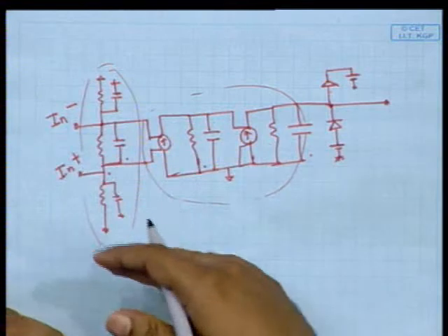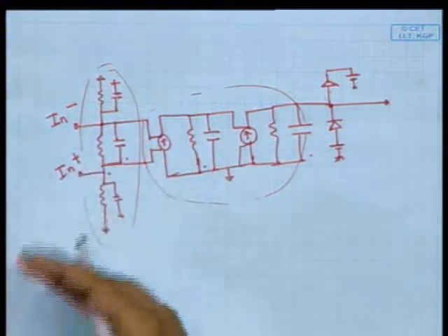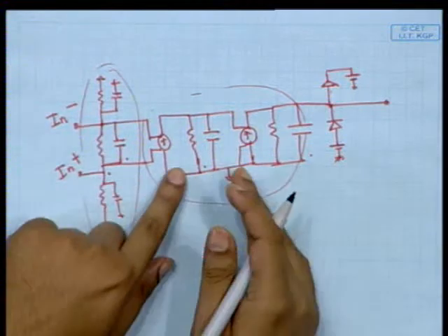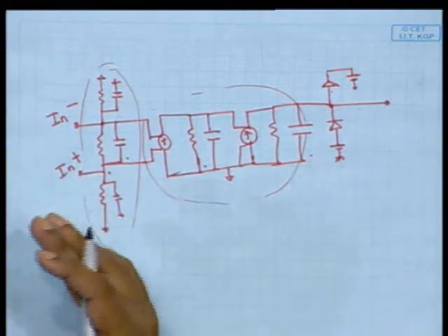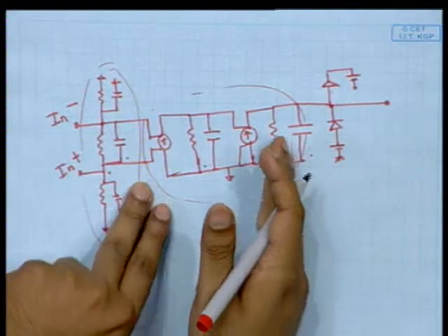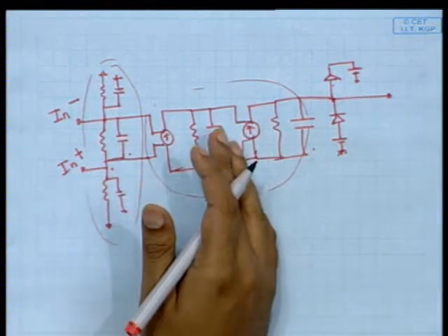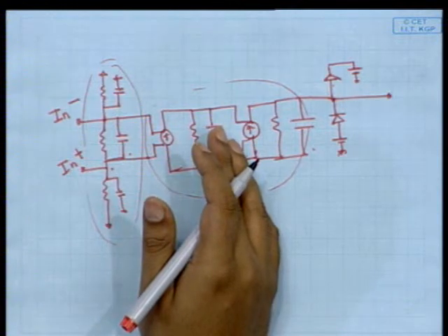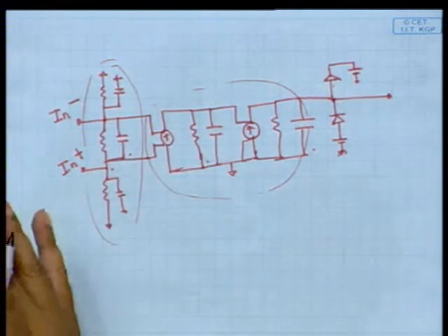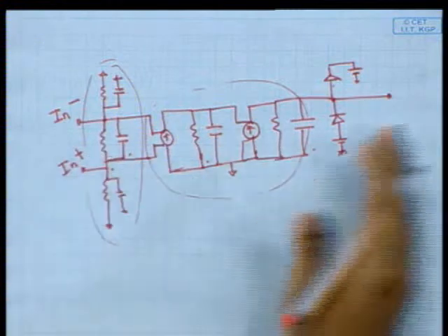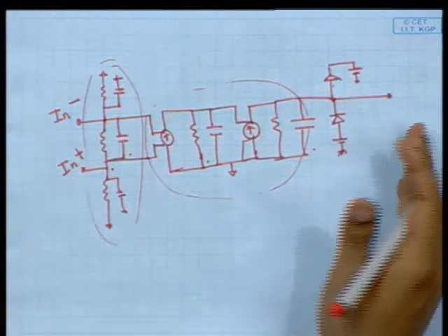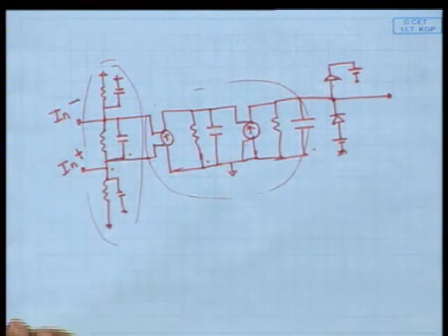So it is applicable for all op amp designs. If you have designed a two-stage op amp, you can calculate the values for this one also. Also, if it is a big design, this same model is applicable for that too. You need only the specifications, and the components and characteristics you want to model, you just go on plugging in. That is the development of a simple macro model.